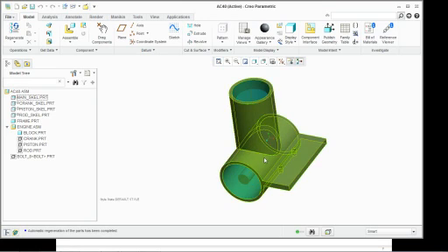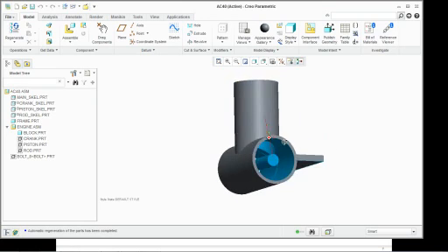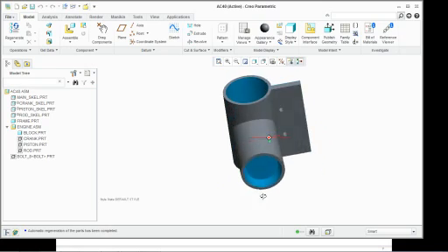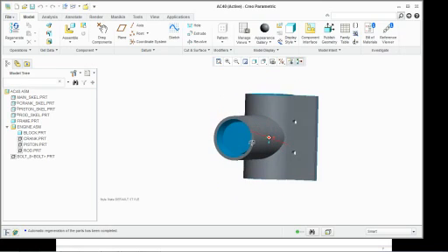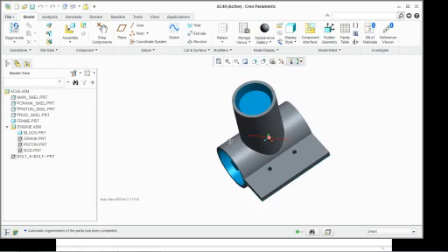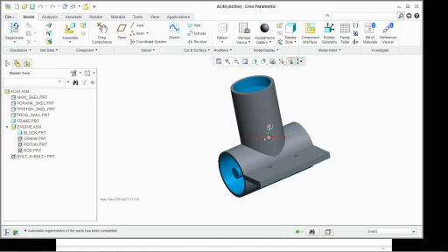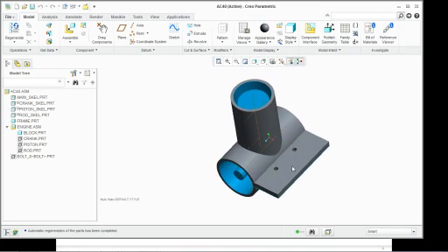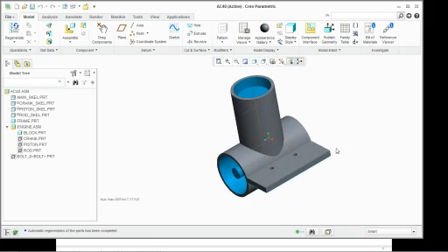Everything in this assembly mates to the skeleton. So notice that this component here did not get longer. The piston is not referencing that other diameter. It's referencing its own skeleton, so it's not going to get bigger unless we edit that skeleton. But everything did update dynamically.